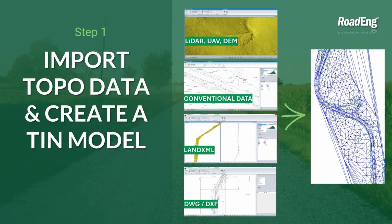So the software works with a whole bunch of different types of topo data. Today, we're going to work with some LiDAR data, but basically we need any type of data that has elevations. And then we take that data with elevations and we create something called a TIN model. Now, a TIN model is a triangular irregular network. It's shown on the right side of the screen, and it basically makes a surface model that we can then work with. So once we've got that surface, we can start to do site design, road design, and do that. And with that, let's get into the software.